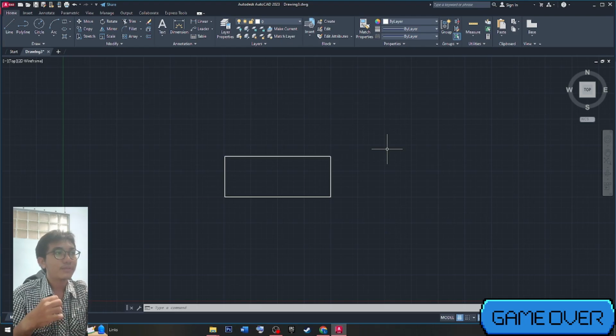Okay, we have to see whether this object is 3D or not. We have to change the view into the southwest view. How? Just drag your mouse to the top right side, and then you can see the north, east, southwest thing, with the square in the middle.